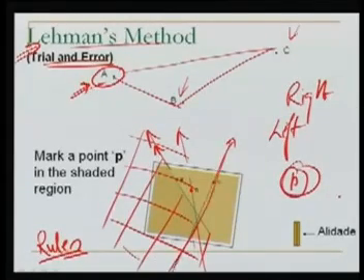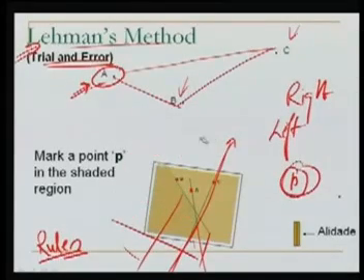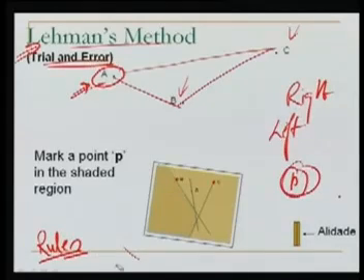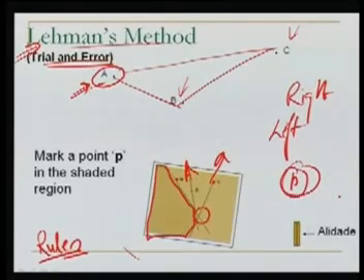Left of this resector also. If we consider all these and left of all these, what do we end up with? Our point has to be somewhere in this area, because this is outside the triangle of error. It is towards the left of all the resectors. Okay, so our point has to be here.